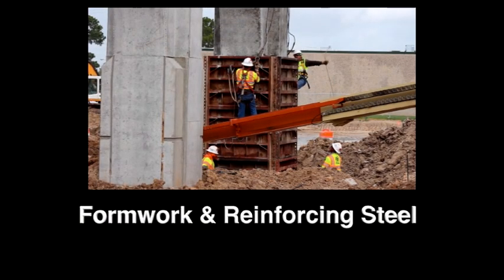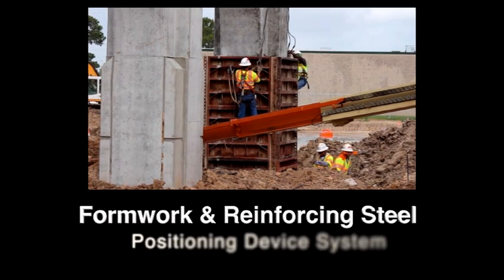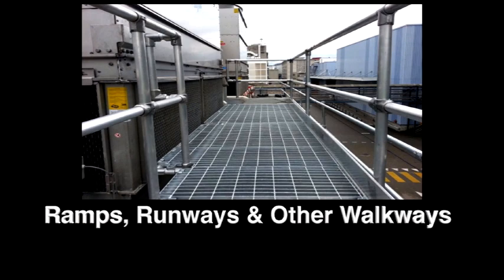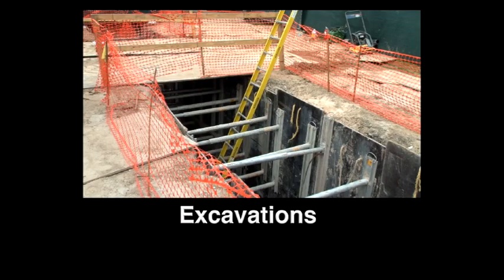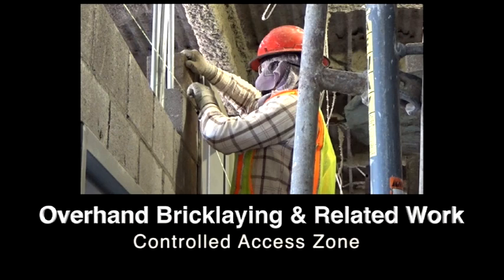Formwork and reinforcing steel: PFAS, safety net, or positioning device system. Ramps, runways, and other walkways: guardrail. Excavations: guardrail, fences, barricades, or covers. Overhand bricklaying and related work: guardrail, safety net, PFAS, or controlled access zone.